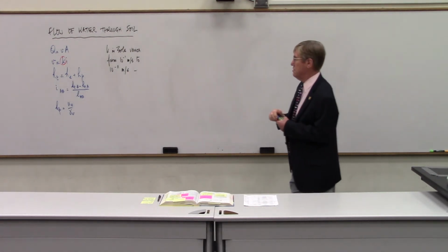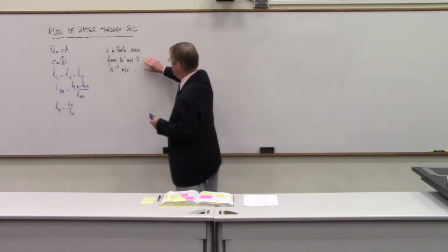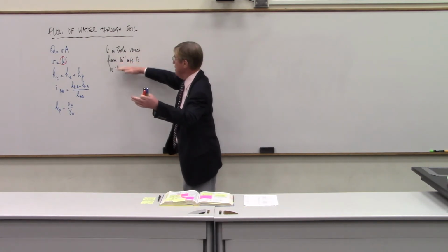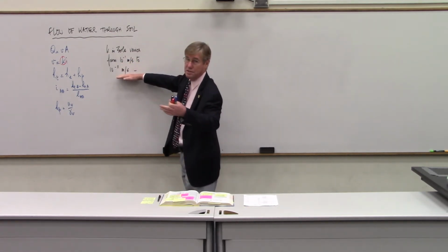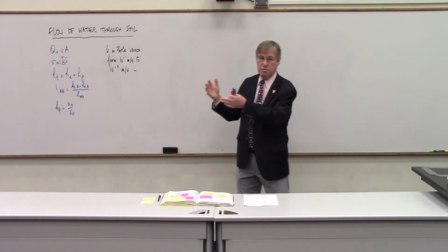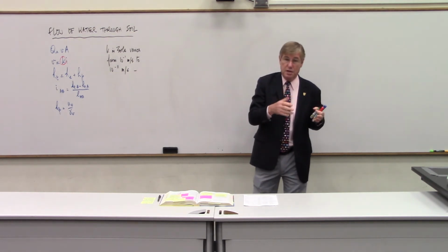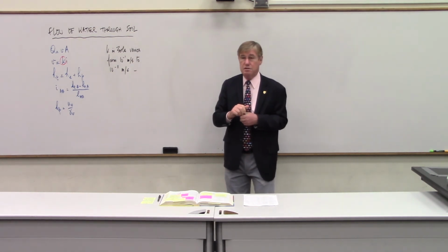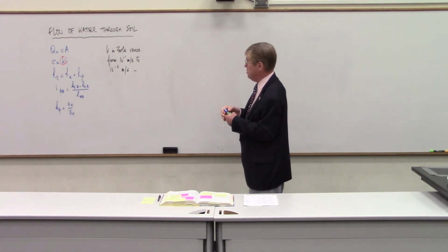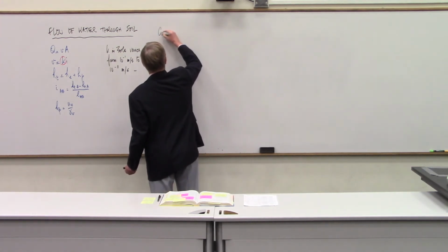It's not going very fast. This would be like sand and gravel at one end, and this would be silts and clays at the other. So typically, we make a distinction between the test we use for sand and gravel and the test we use for silts and clays. The one you're doing in the lab is for sand and gravel because it's a much simpler test, and we will start with this one. It is called the constant head permeability test.